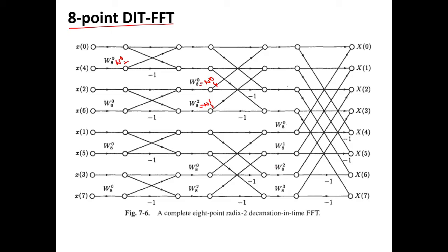What I am trying to say is that you can use this nomenclature also, W08, W28, but personally I feel comfortable putting the twiddle factors in an easier fashion when I am performing longer numericals. When I am performing 4-point DFT, it is fixed in my mind that I just have to put the serial numbers W0123 in that fashion. Now again, since we are doing 8-point DFT, we are performing four 2-point DFTs.